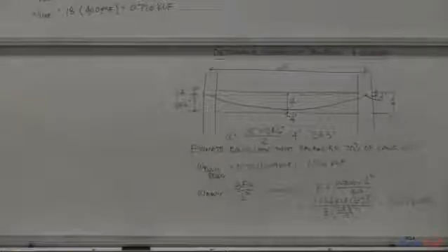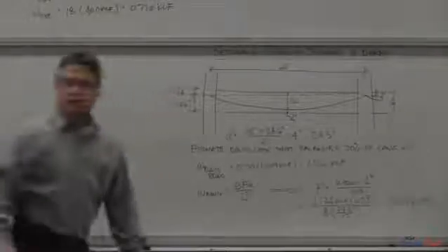Okay, remember, this is what makes design different than analysis. I could just give you this, but I'm not going to. I want you to prove that you could get close, that you could get to a good starting point. And all I'm telling you is balance 70% of the concrete weight and provide 250 psi over the section.